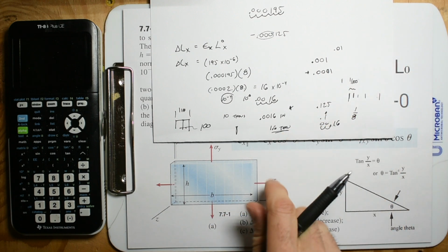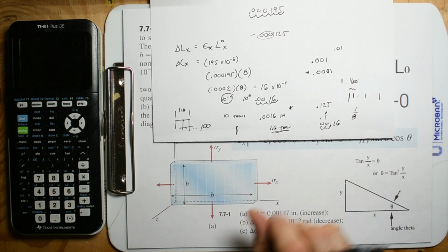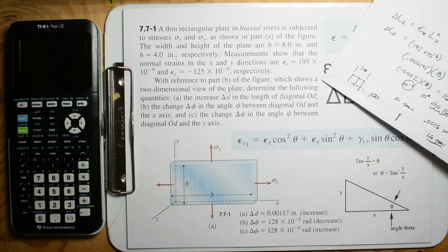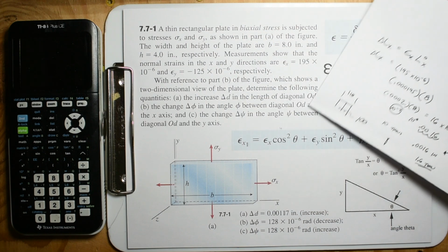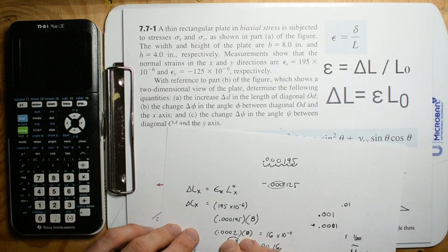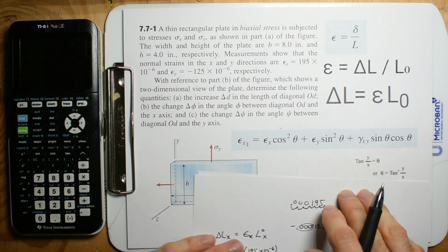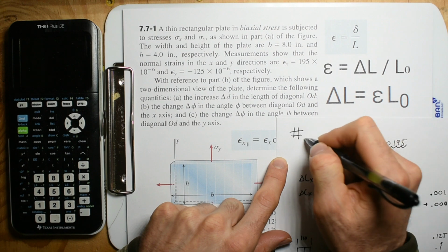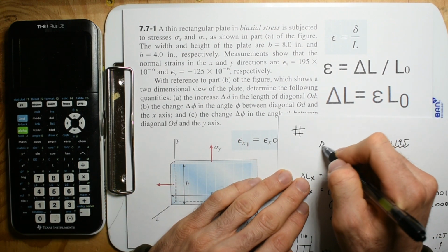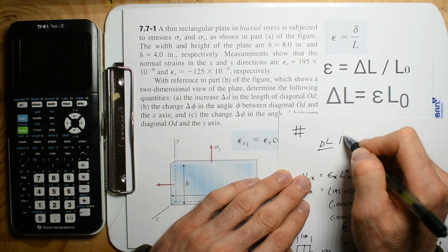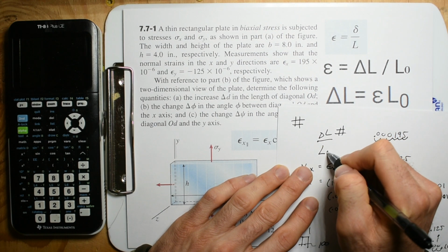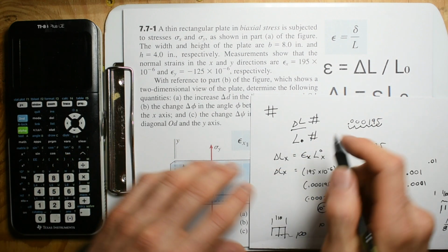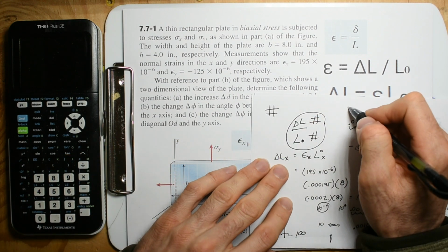I'm glad I spent about 5 minutes on that, because that's the tricky part about material mechanics: getting used to very small numbers and associating them with very big numbers. But the main goal of material mechanics is saying that this material can only withstand a change in length of that value per the initial length. Change in length can only be so big if I know the initial length. And that ratio is going to be the same for all steel. That's why this ratio doesn't change, and we call it strain.